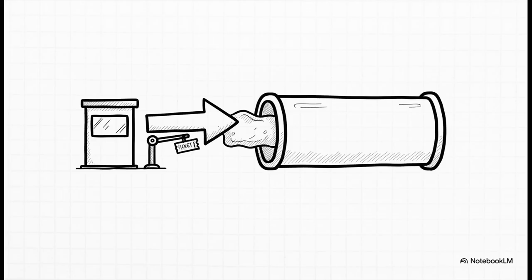And the formula for it? It's beautifully simple. Pressure times volume, or PV. This is the work that was done to get that fluid into our system. It's the ticket that bit of fluid had to pay just to get in the door. So the big takeaway here is that any fluid that's flowing has this extra little piece of energy that we have to account for.